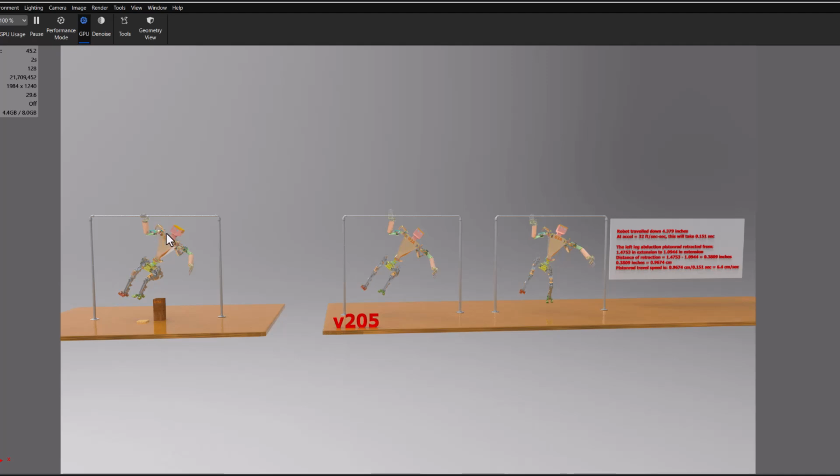So about as much of the weight of the robot is on this side of the hand as is on that side of the hand. So when the robot starts falling, it needs to alter itself, otherwise it's going to land on its left foot and smash its hip into the ground. So we're going to talk through, can the robot do that?